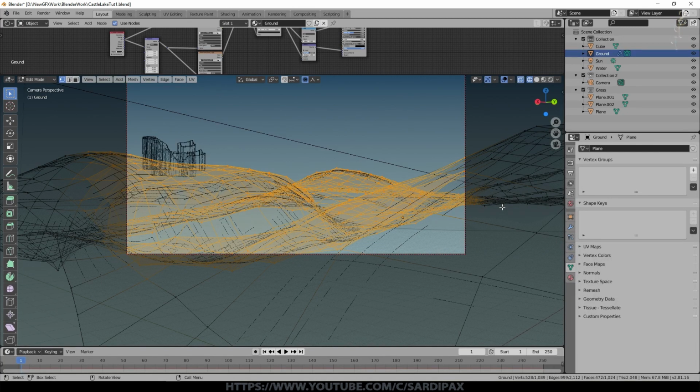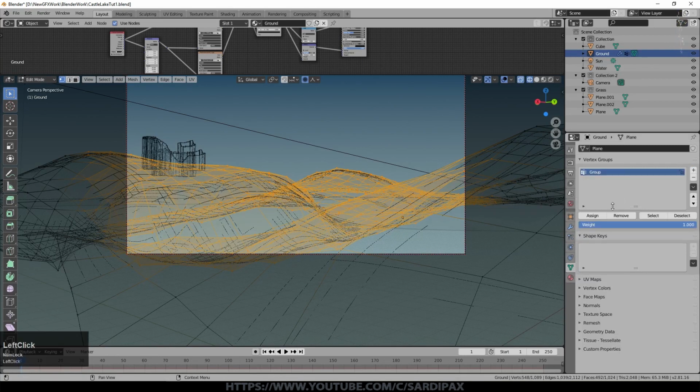I'm not going to worry about that right now. I'm going to do it with just the number that I've got right now. So that's fine as far as it goes. You need to select slightly outside the camera, and so everything that's within the angle of view of the camera is currently selected. So I'll add a vertex group and I'll assign it. We'll call that camera view, bearing in mind that if you do this way, you may need to redo it if you move the camera at all.